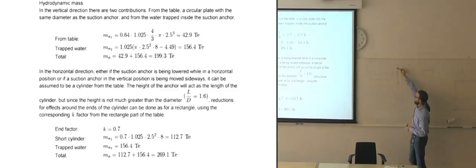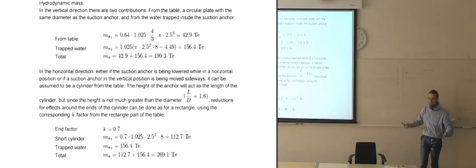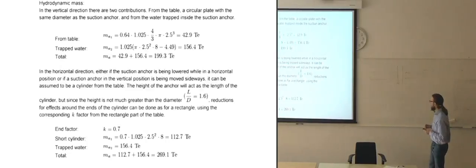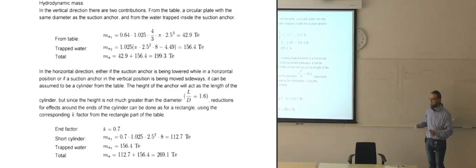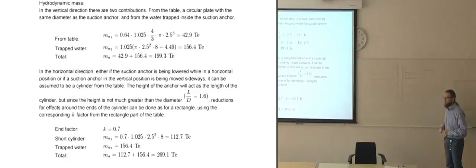So that when you're lowering it down with this one, all of the weight is on this crane, so you're lowering it straight down, but you're not getting all of this added mass that you would get if you were flipping the plate already. So you can lower it almost all the way down, and then when you're almost to the bottom, this one starts pulling upwards, and then you can sort of get it level on a horizontal plane. And then you only get your added mass for the last couple of meters, or 10 or 50 meters before getting it into place. So it's a much more controlled situation when you're doing your lift.